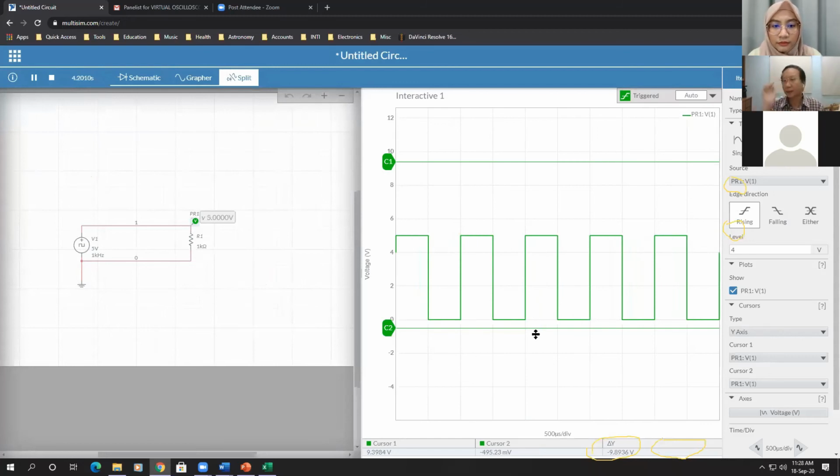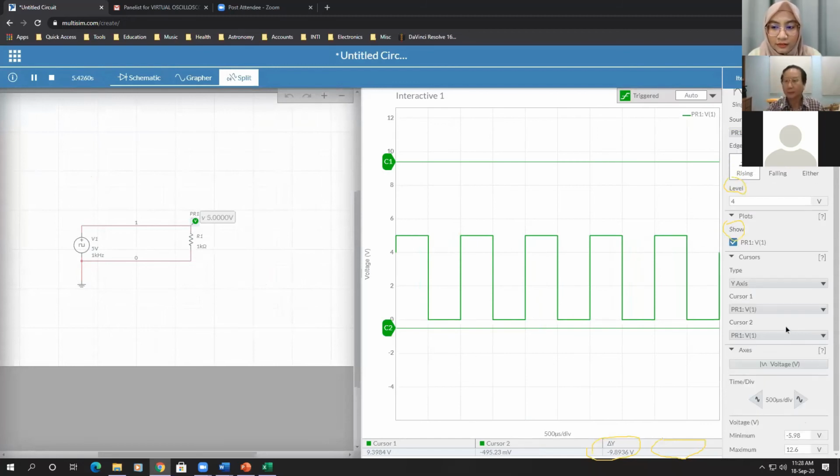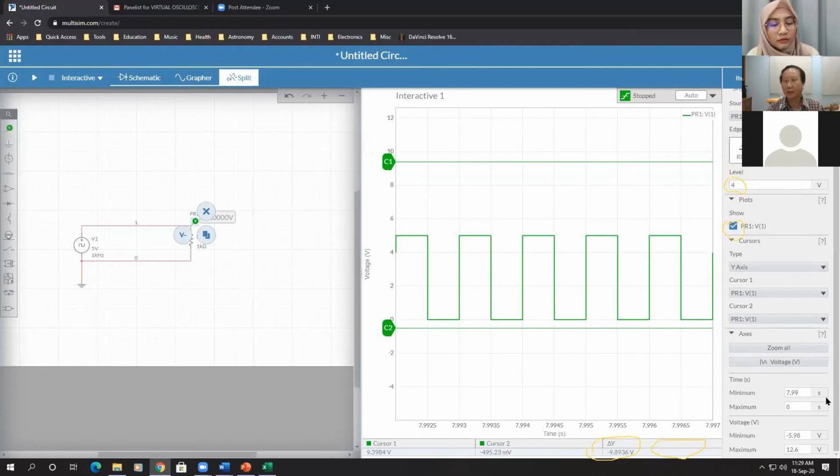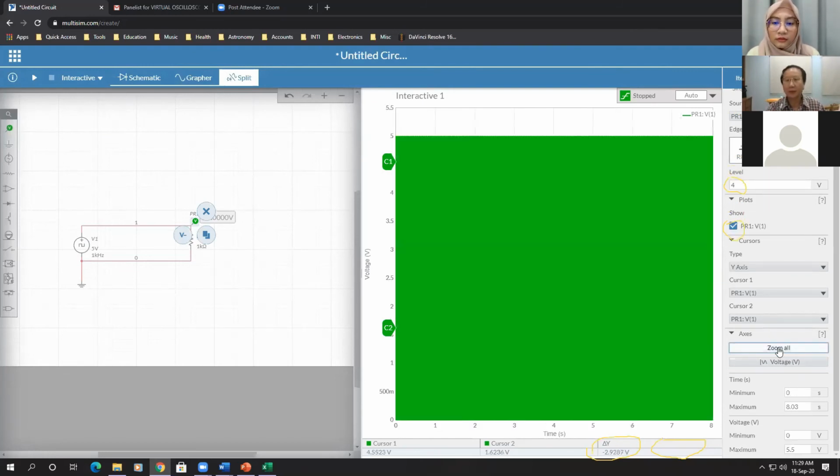All right. So like a normal scope, you can also use the function here. This is like a button. You can actually zoom everything at one time, zoom everything, but it's too complicated. You can also change the minimum and maximum. Let's say I change this range to 10 milliseconds.